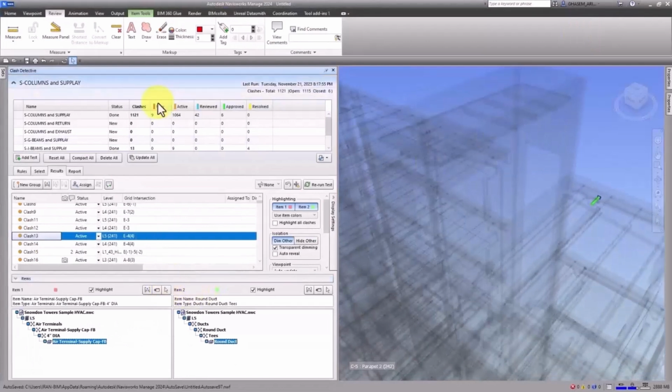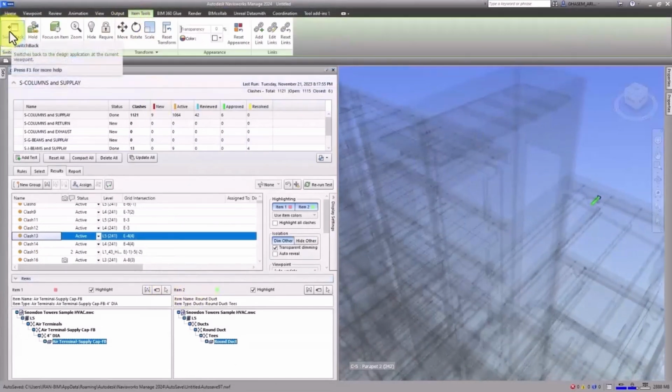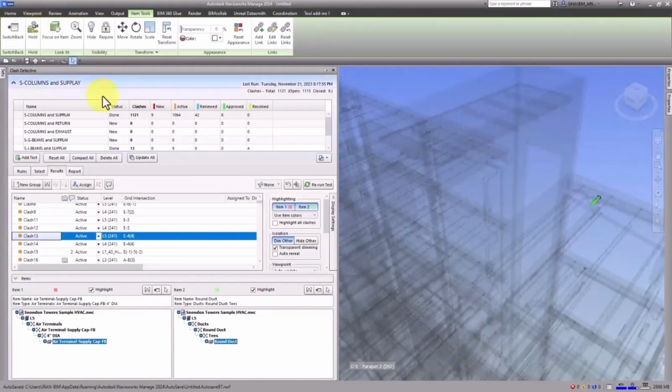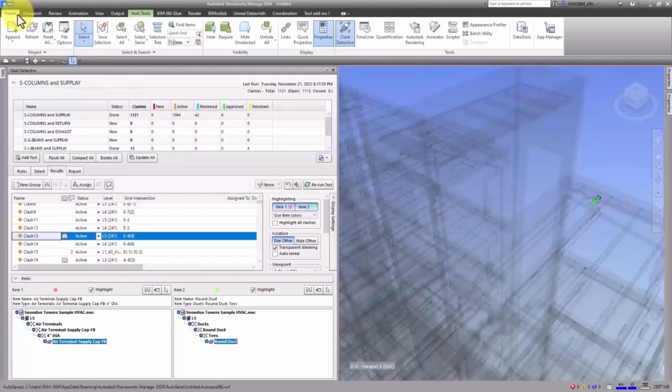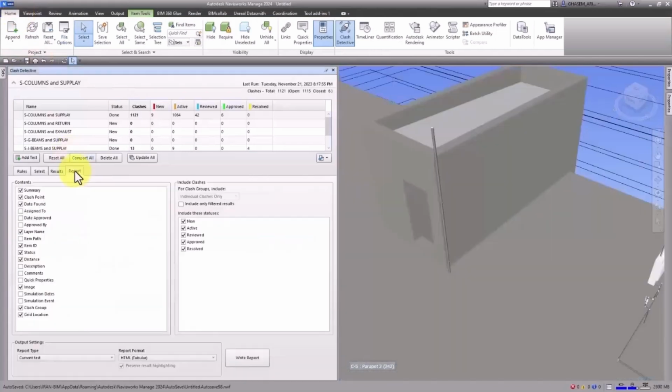So this switchback item can be useful in this kind of situation. Or when you select with this item, in this section, you can have switchback as well. You can use it here too. But be careful, we don't use switchback except when there are only 2 or 3 clashes, or when we have the main clashes. When we have many clashes, like now, for example 1000 clashes, we can't use switchback. It wastes all the time. All of these updatings and exportings are really time consuming.